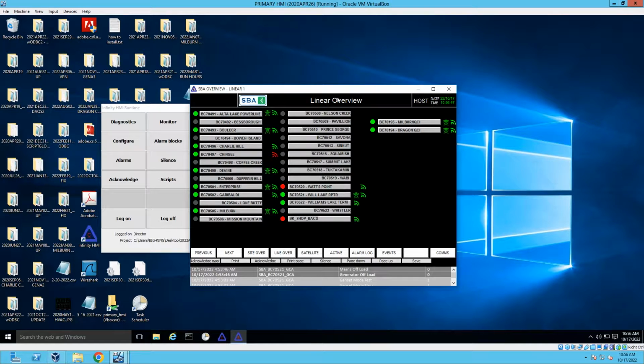This opening screen outlines our various sites with a site ID number and a site name. On the left, we have an indicator as to whether our communications are turned on or off. This is important because occasionally we have sites that are offline due to scheduled maintenance and we don't want our network operators opening tickets unnecessarily. To the right of our site button, we have an indicator that confirms site utility power is adequate, as well as an indicator that communications are functioning correctly. This allows us to identify power and communications issues at a large number of sites with a quick glance.